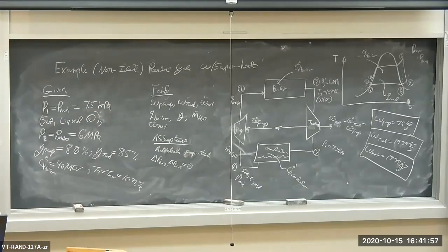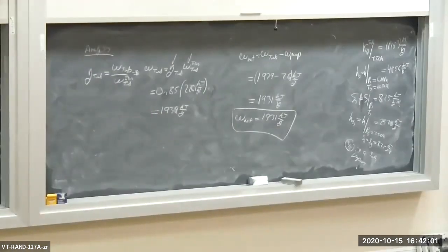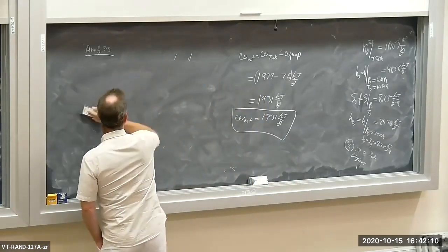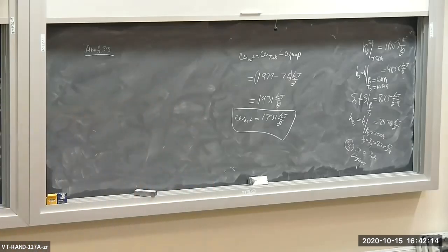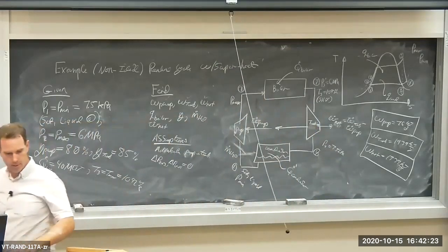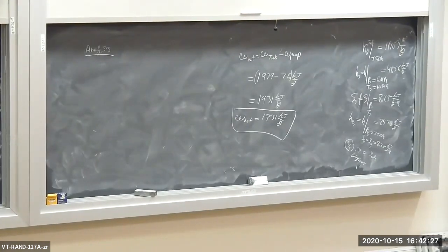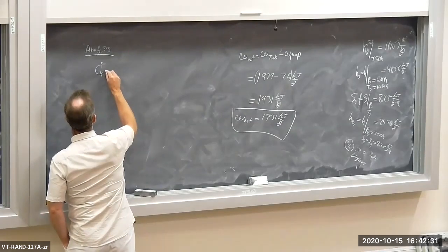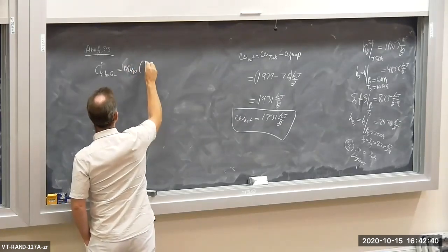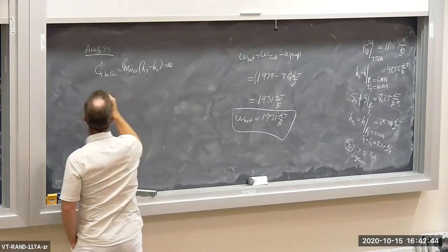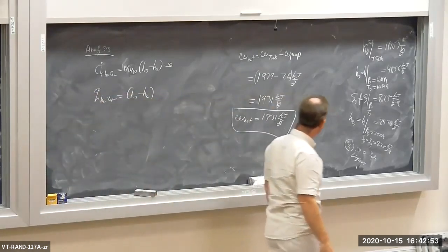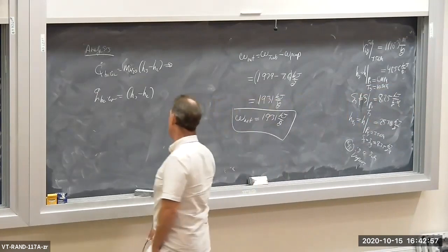Let's find the heat addition to the boiler, Q to the boiler, that's per unit mass. Well, application of the energy balance over what process? From the boiler inlet to the outlet. So apply the energy balance to the boiler, from state 2 to state 3. There's no work interaction going on. I get Q dot boiler equals m dot for the H2O, H3 minus H2, or if you like, Q boiler equals H3 minus H2. Now I have H3 somewhere. There it is, 4856. So what's H2? I don't know what that is.